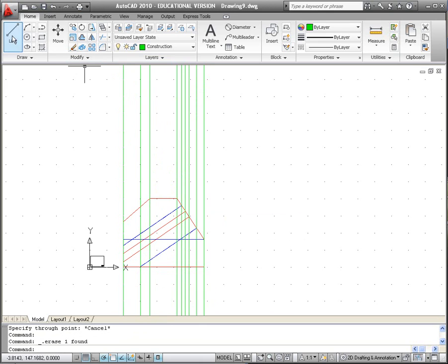So if I look at my upper view, I'm going to draw my visible stuff first. So I'm going to select the visible layer, come up here, select the line command, and then I'm going to draw across from here to there. This is one of those deals where you can go past and trim. It may be better for you to do that, or you could turn on ortho. I've got that one set up.